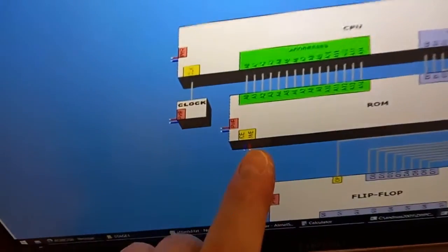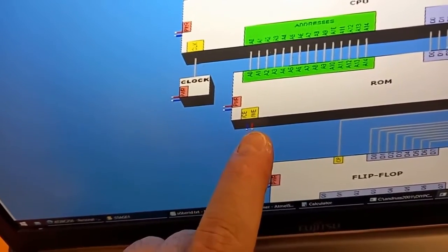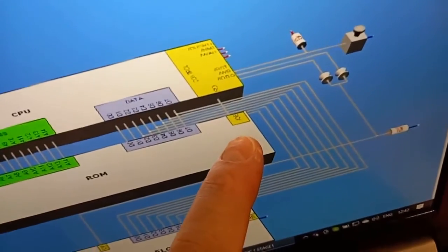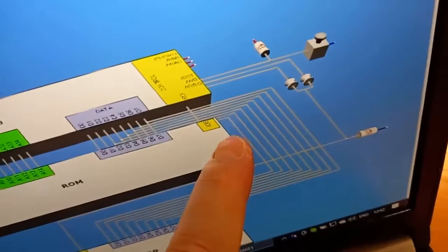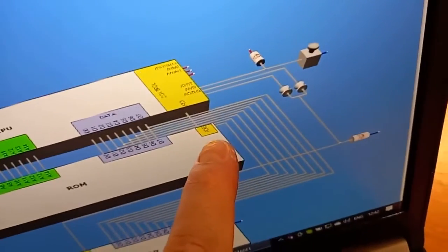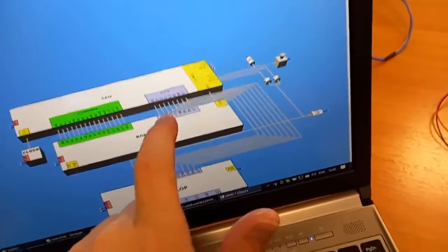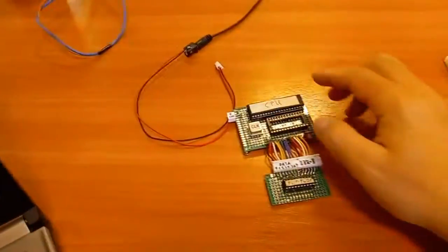The writing we disable statically, and we are not going to enable it on the computer, we are not writing anything. Chip enable we connect to enable, so we keep this chip enabled all the time. Power, we connect ground and plus, and output enable is switching. At the computer sometimes the output is enabled, sometimes disabled when the CPU is using this bus, to avoid conflict.